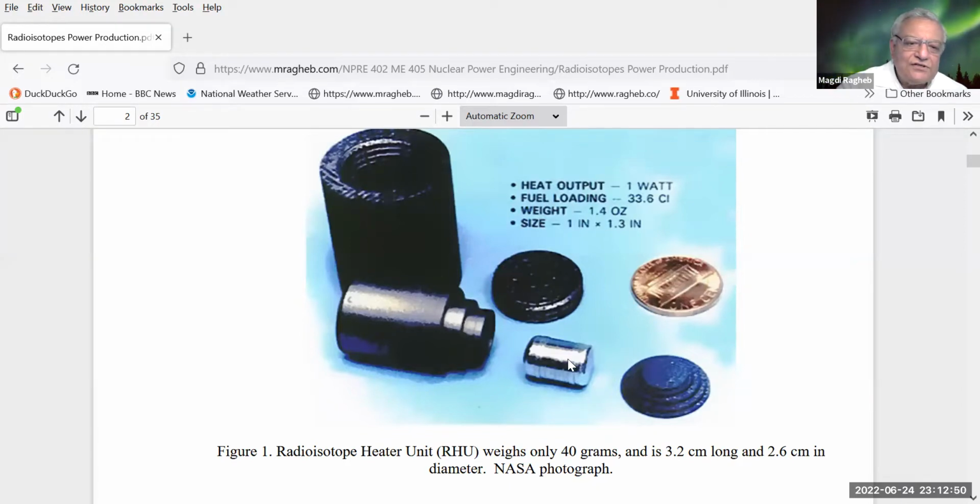When you are launching it into space, there have been situations of the launch failing, and you don't want the plutonium to fall down and spread itself on the surface of the Earth if the launch fails. So the graphite provides a protection first against gamma ray emissions from the plutonium-238, as well as taking very high temperatures. Let's say they can withstand a fire.